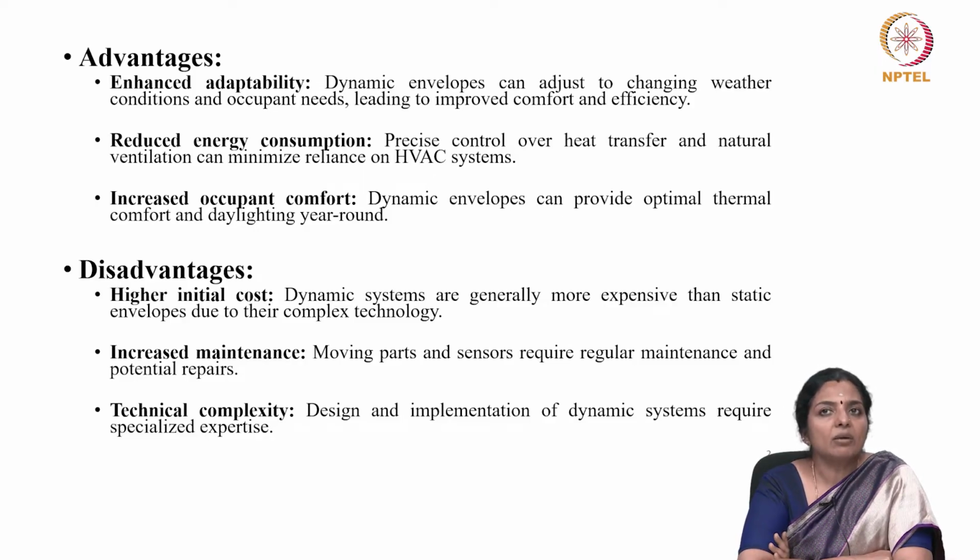The design variables such as geometry, glass reflectance, the thermal mass, the shading devices, etc., also affect the energy performance. Improving these design factors can result in 46.8% reduction in yearly space cooling energy consumption in hot climates.